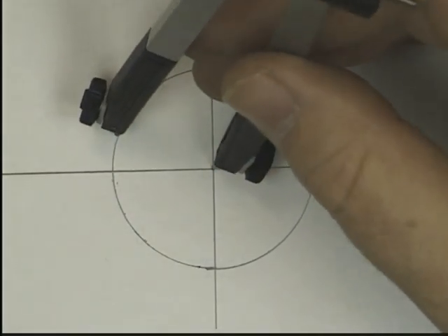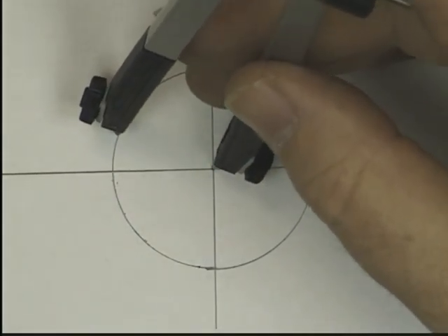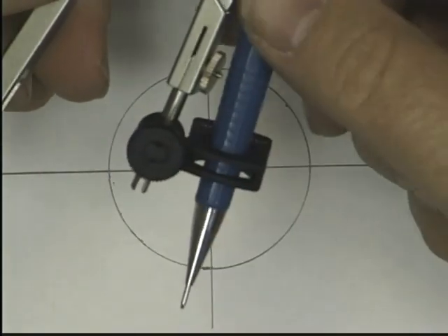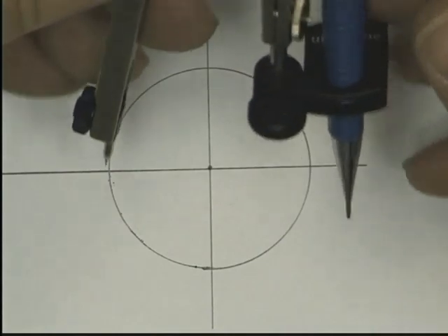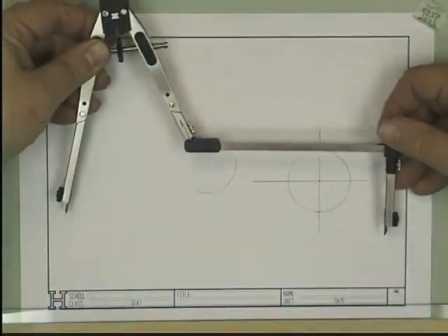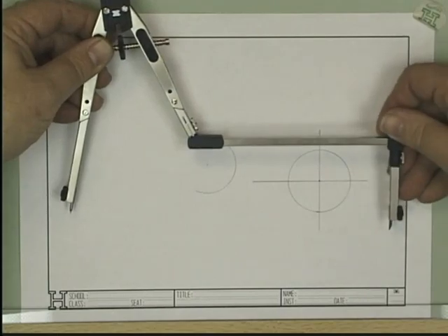And we saw that we could use an adapter on the compass so that we didn't have to use the wedge-shaped point. We could use a regular uniform lead holder. We also saw how we could use a beam extender or a beam compass to draw very large circles. Then we talked about scales. Remember, I'm the ruler here. If you want to measure something, you use a scale, not a ruler.